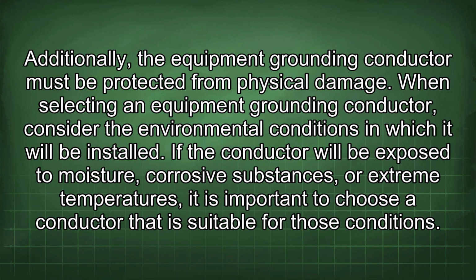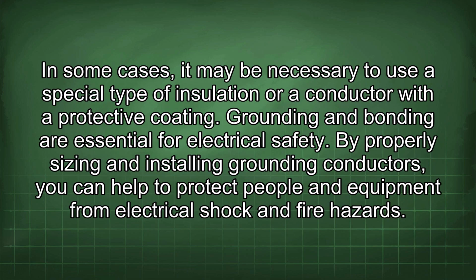When selecting an equipment grounding conductor, consider the environmental conditions in which it will be installed. If the conductor will be exposed to moisture, corrosive substances, or extreme temperatures, it is important to choose a conductor that is suitable for those conditions. In some cases, it may be necessary to use a special type of insulation or conductor with a protective coating.